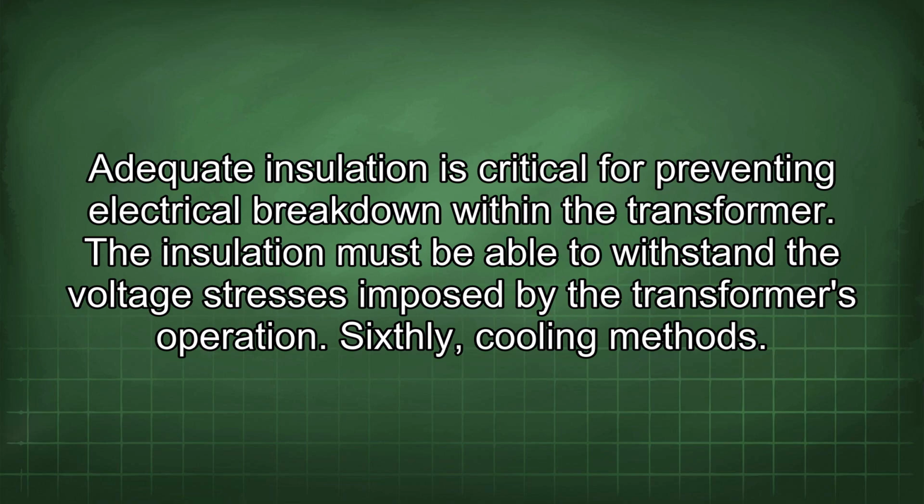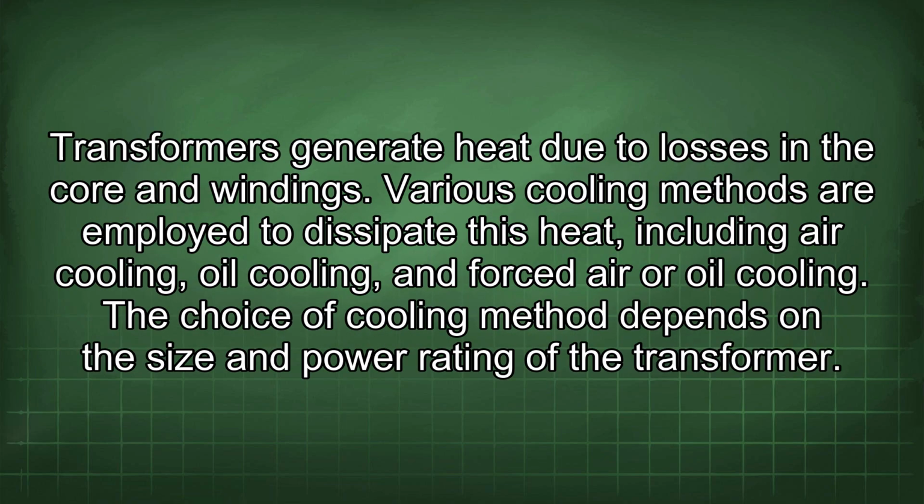The insulation must be able to withstand the voltage stresses imposed by the transformer's operation. Sixthly, cooling methods. Transformers generate heat due to losses in the core and windings. Various cooling methods are employed to dissipate this heat, including air cooling, oil cooling, and forced air or oil cooling. The choice of cooling method depends on the size and power rating of the transformer.